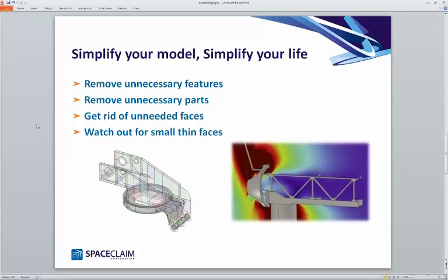And so what do I look for and what do I think about when I think of simplifying your models? Now, the problem with just saying simplify and just saying defeature is that it can mean so many different things to so many people. And that's why I like a tool like SpaceClaim, because it empowers you as the analyst to make the changes you need for your mesh. If you want to remove rounds, remove the rounds. If you just want to get rid of holes or just want to get rid of some small faces and merge them together, just do that. A lot of times you've run enough of these to know what to look for. I'll point out a few things that I've heard that people look for, and also I typically look for in models, such as really tiny faces that can bog down a mesh, also thin faces that may be there, larger, thinner faces, which may cause issues.